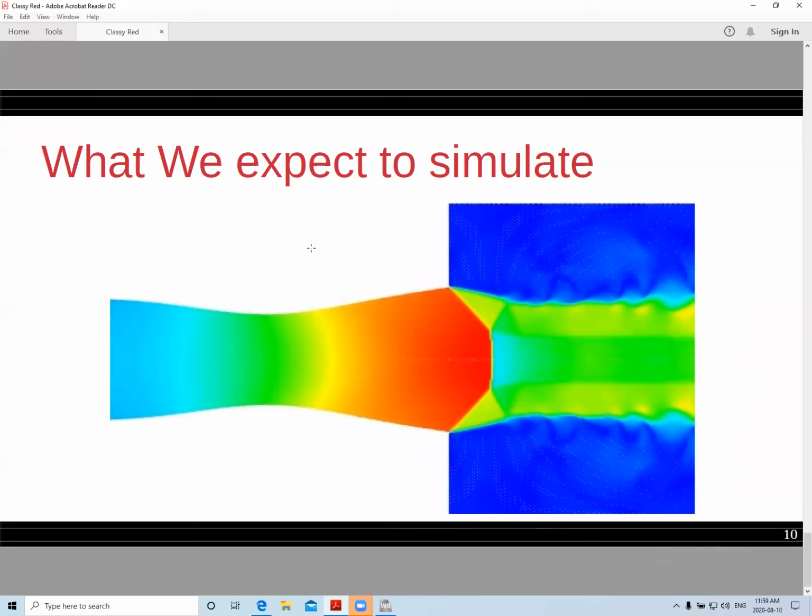What you expect to see is that the Mach number of the flow continuously increases from the inlet to the throat, and it reaches 1 at the throat. In the diverging part, it keeps increasing toward the exit of the nozzle, and in the tank, because of the pressure difference, you will see the oblique shock occur.